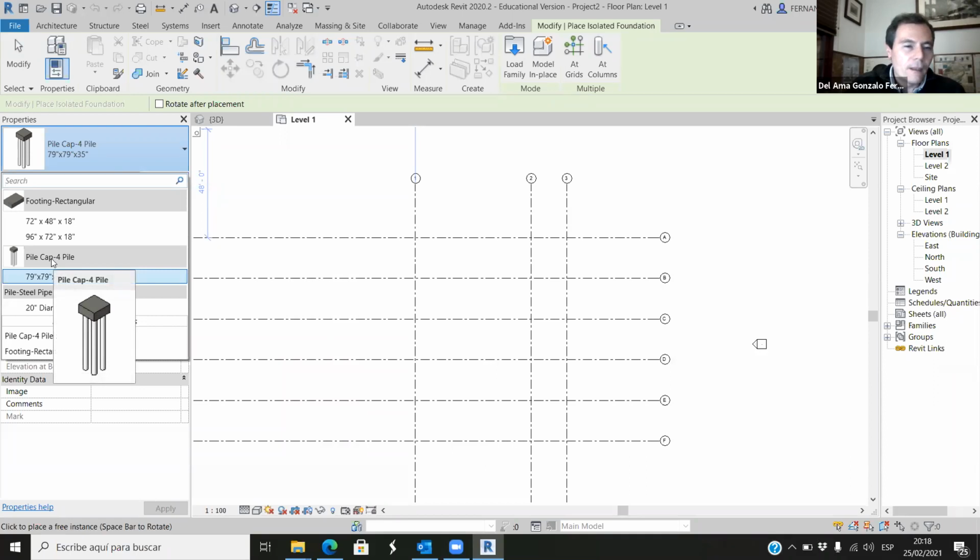We have to calculate this, but I want to show you that, depending on the soil, this is the first thing we have to understand when we are designing a building: what kind of soil we are working with. Do we have rock a few feet underneath, or do we have to go deep with 40, 50, 100-foot piles to find the solid rock?